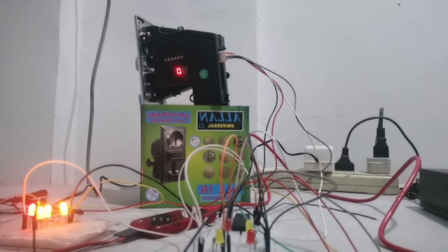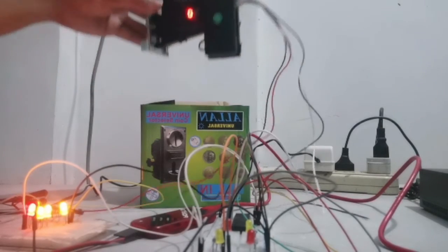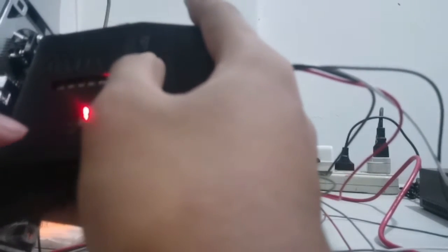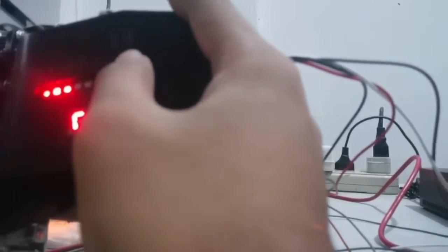So since this is for the 5 peso coins, we'll have to reprogram our coin slot to recognize the 5 peso coins. So in order to do that, we'll have to long press here and still recognize one coin slot. And in this coin slot, I actually want 3 samples because I only have 3 samples of 5 peso coins. And for the pulse, let's retain it at 1. And for the sensitivity, at default.